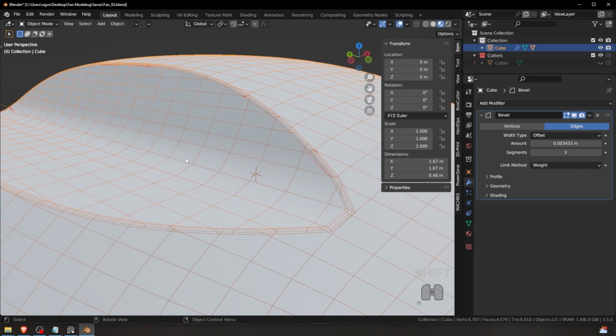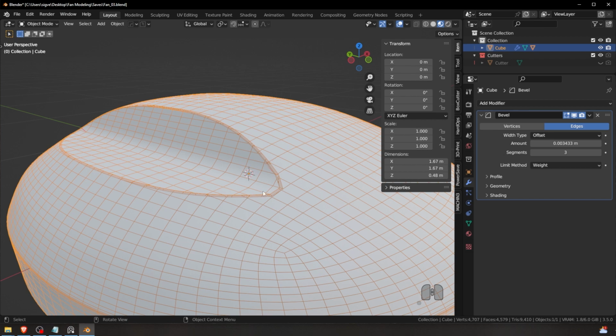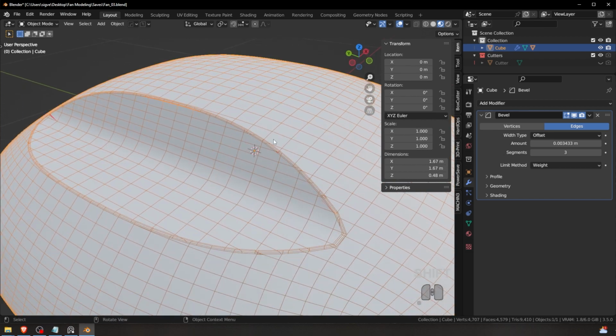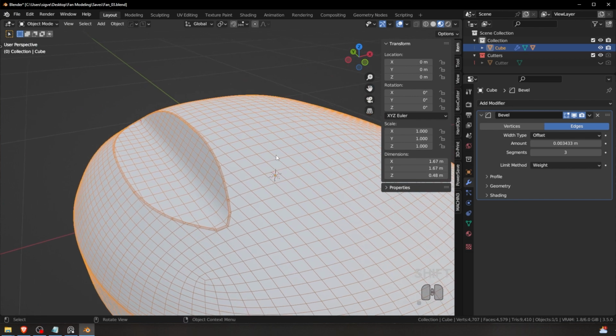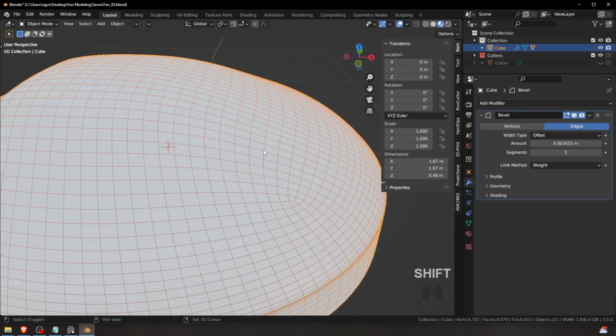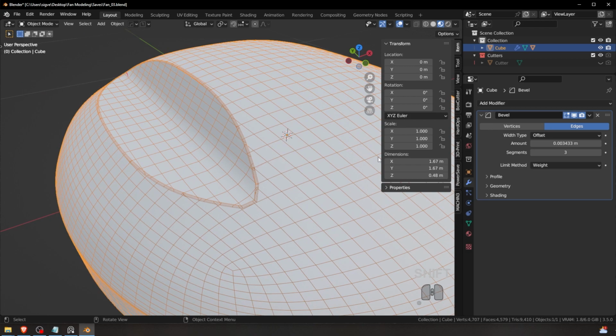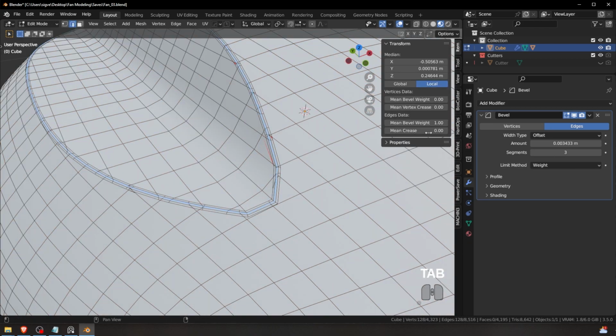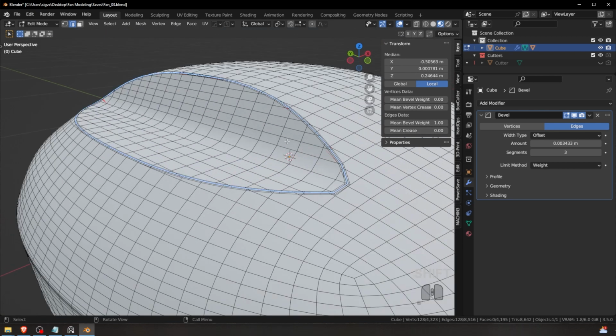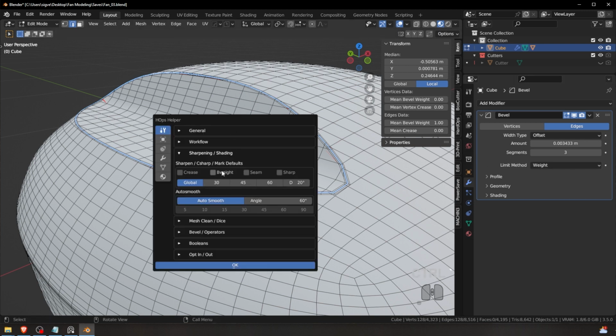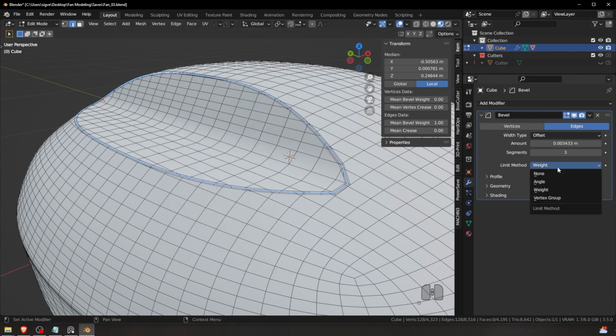Now this isn't beveled, it's straight, and now all these edges around are beveled actually. You see? That's what we wanted. But now if we were to cut something else, we would have to do the same thing. Just select it and increase the mean bevel weight. So we got a lot of control with this one, but it's a little bit more additional work because you need to specify the angle still if you want to keep this on, so it adds automatically weighted normals. You would have to still specify the angle here, and that's basically the same as simply running angle at like 30 degrees.